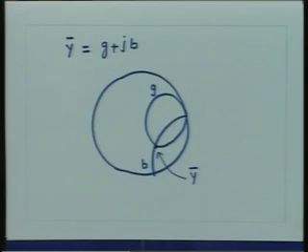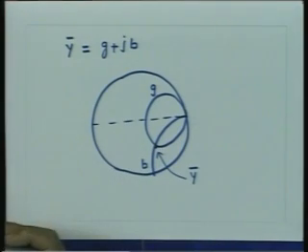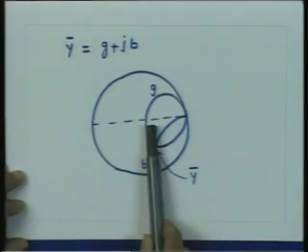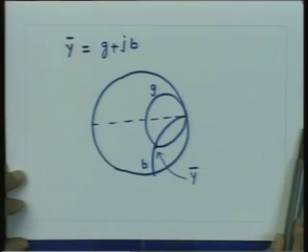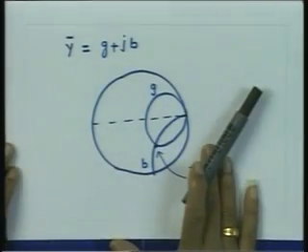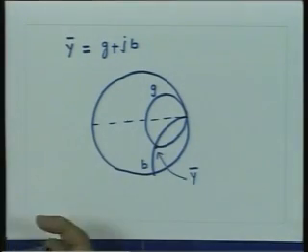However, now if I want to find out the complex reflection coefficient, remember now the real gamma axis, or the real reflection coefficient axis, is not on the right, because we have kept the Smith chart fixed, and for admittances the coordinate axis has been rotated by 180 degrees.